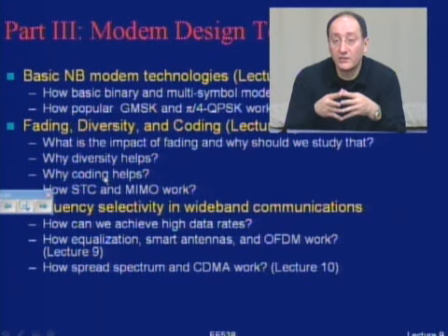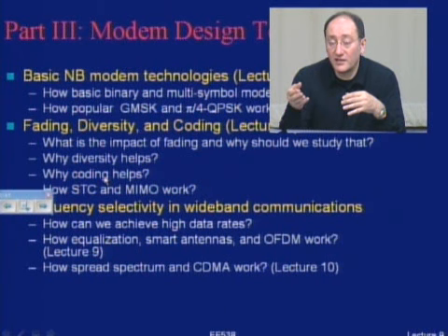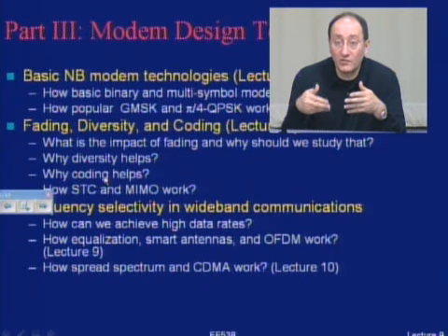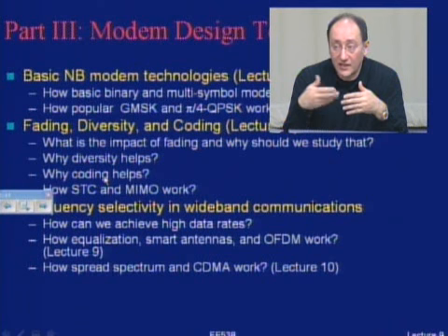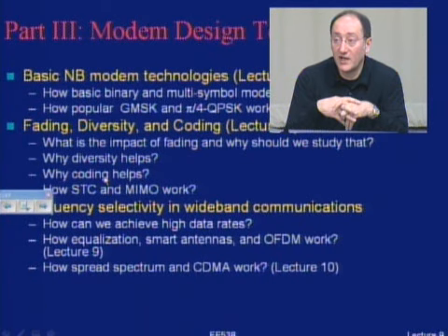communication techniques or wideband modems. Wideband modems are the ones which are operating at a time that your data rate is comparable with the inverse of the RMS multipath spread of the channel. Narrowband is the time that your data rate is less than like 10% of the inverse of the RMS Doppler spread of the channel, if you want to say.